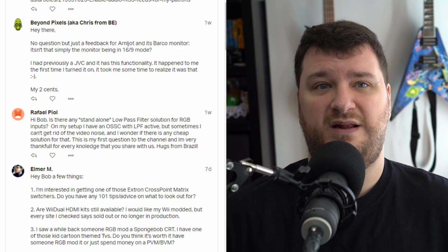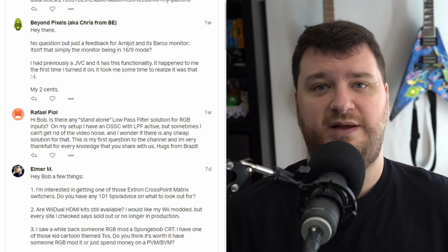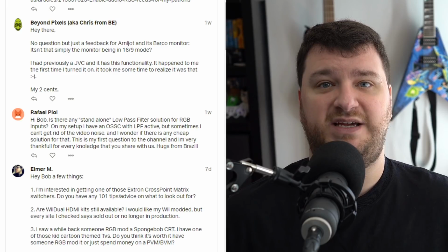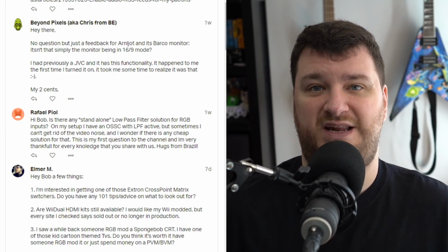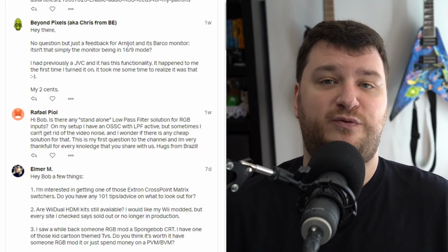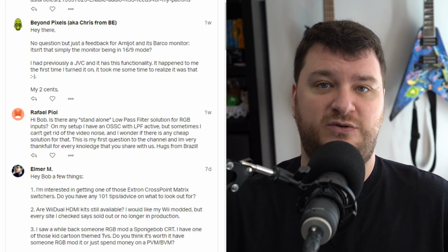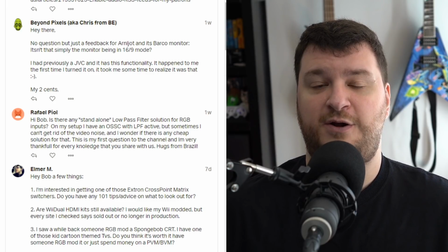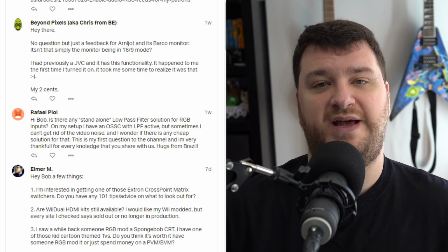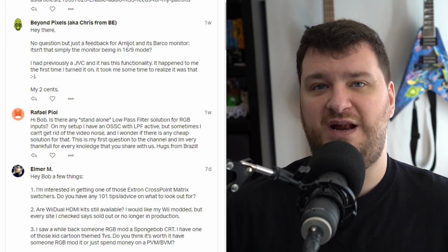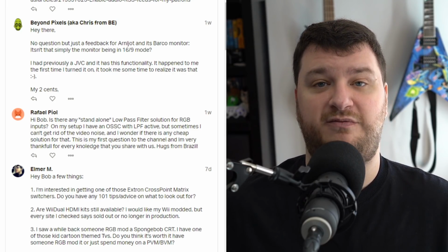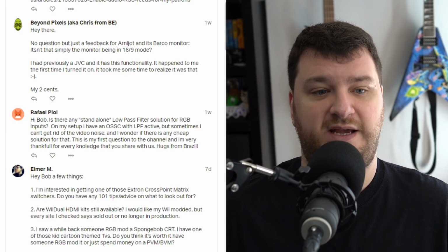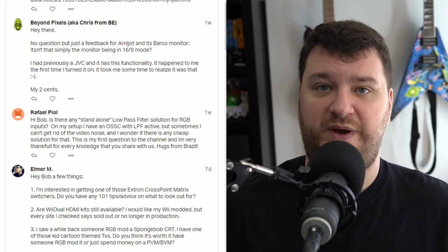If you do, then I'm not really sure what it could be, but if it's something like a Sega Genesis that's not modded, you're probably always going to get noise because they're just inherently noisy consoles. And don't forget, too, that when you're scaling these 240p signals to 1080p, you're scaling the noise as well as the signal. So any little bit of noise that's probably barely noticeable on a CRT is going to be very noticeable on an OSSC.